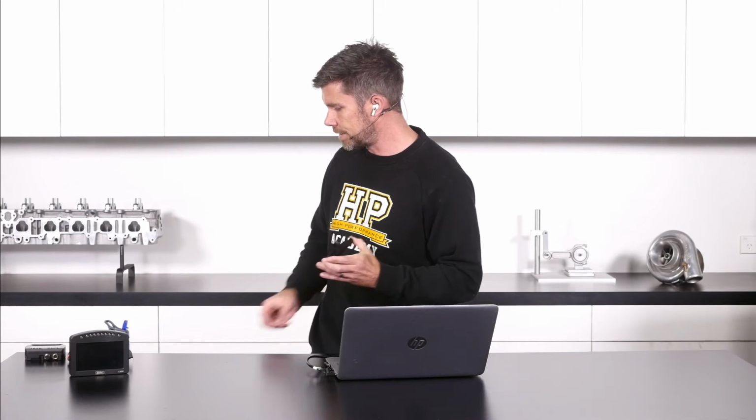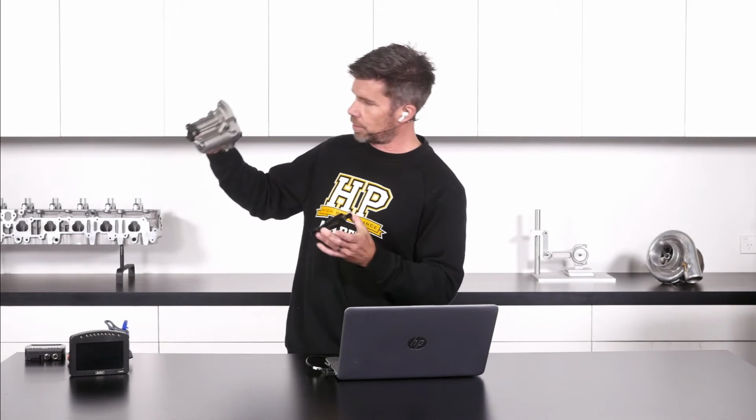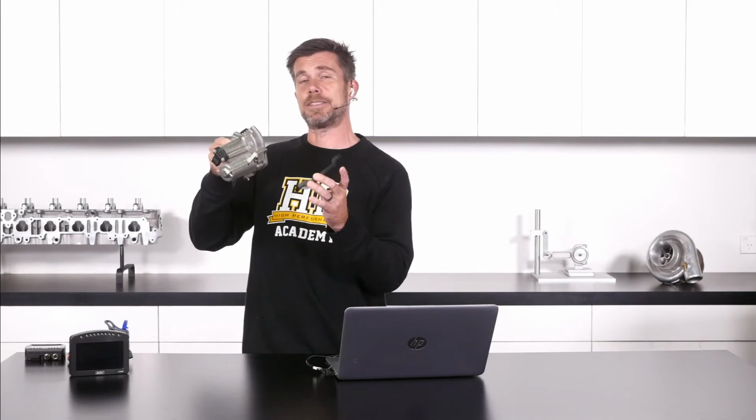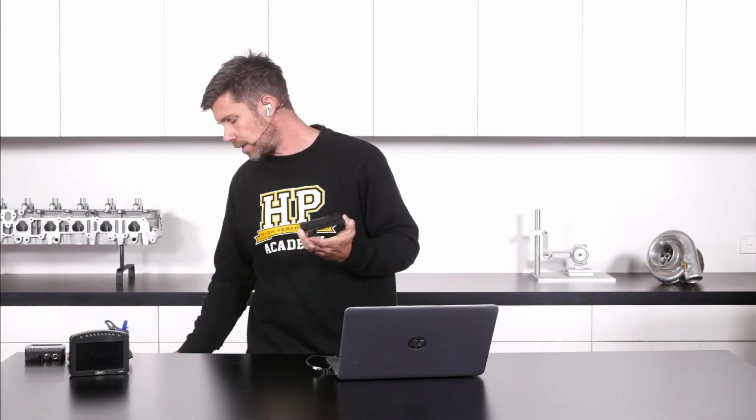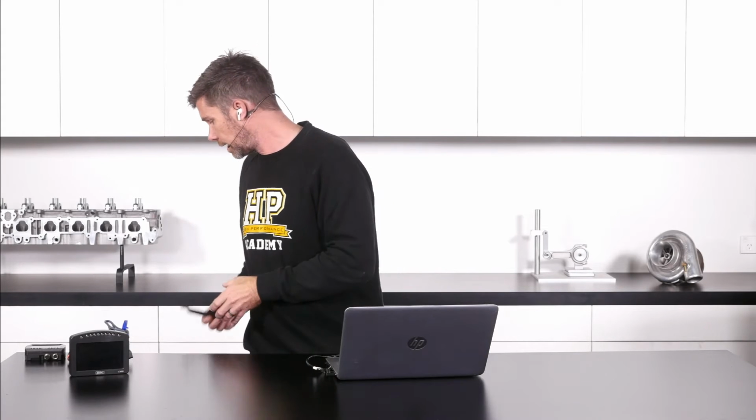That basically adapts the drive-by-wire motor. I'm actually not quite sure exactly how that ends up working, but that adapts onto the drive-by-wire motor and then mounts onto the air conditioning bracket. However, there's a little bit more to it than just that as well, because we also needed to make sure that the bell cranks for both the throttle body as well as the drive-by-wire motor, the motion ratios were aligned and everything was in the right place.